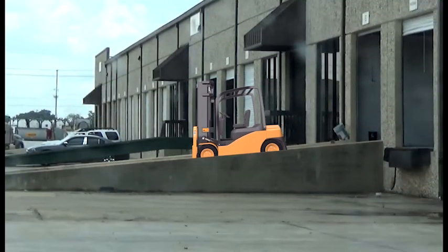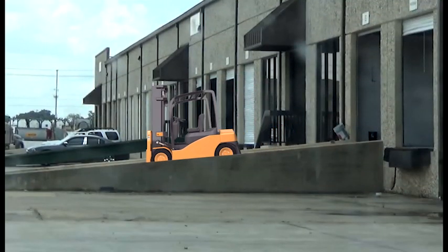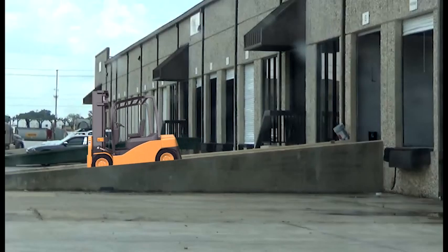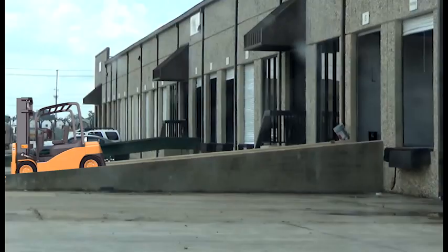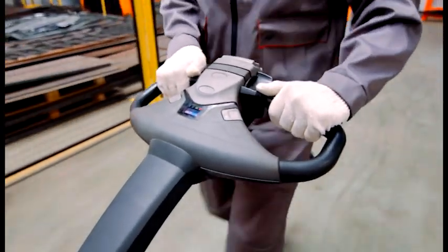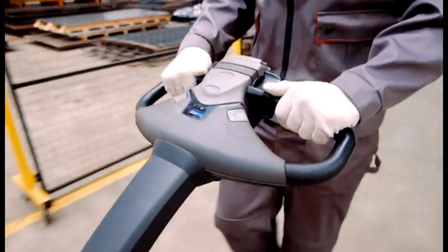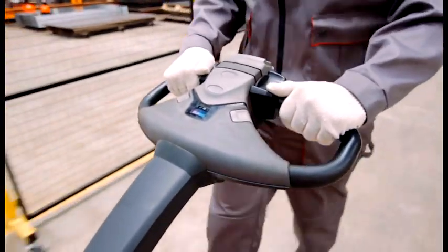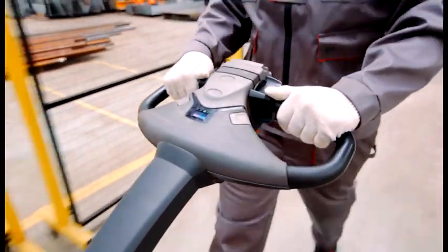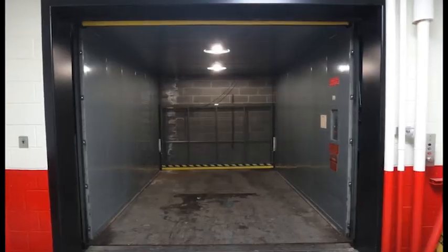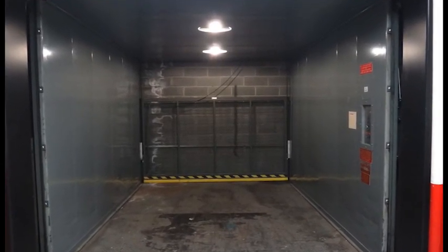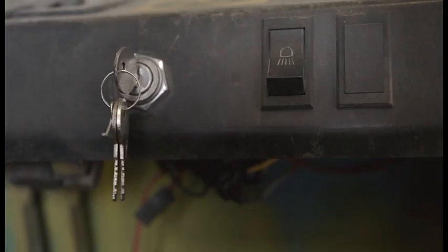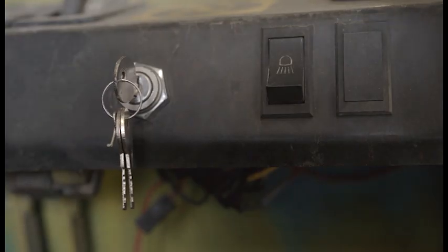When traveling without a load on a ramp or incline, the forks should always be pointed down grade, regardless of the direction of travel. When walking with a pallet truck, with or without a load, the forks should always be pointed down grade, regardless of the direction of travel. Approach elevators slowly and enter squarely after the elevator car is properly leveled. Once on the elevator, neutralize the controls, shut off the power, and set the brakes.